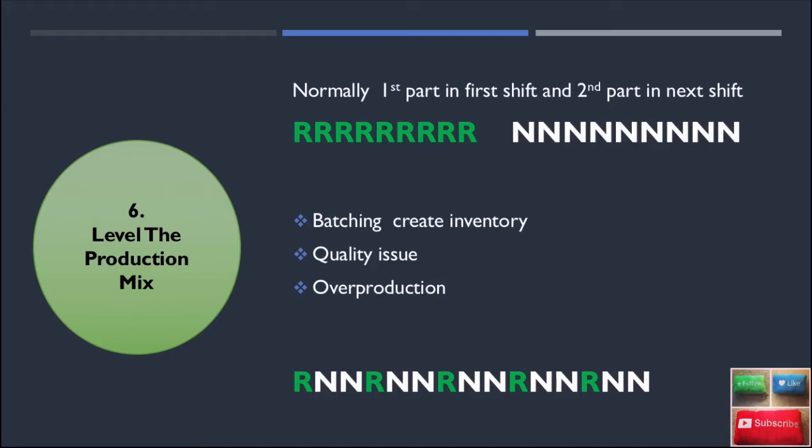And when you create a small batch size, you don't need to create a large inventory for your raw material. This is the next benefit of creating a production mix. Also, you can deliver the different varieties of the product from the start. So you have to do this production mix in lean manufacturing. But while doing this you need very rapid setup time, so to implement this you have to reduce the setup time. This is one of the challenges to follow these steps.